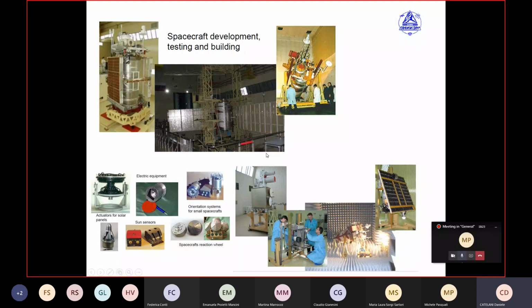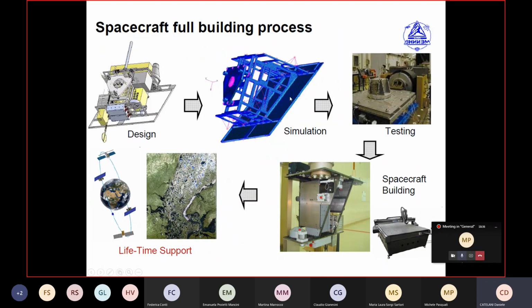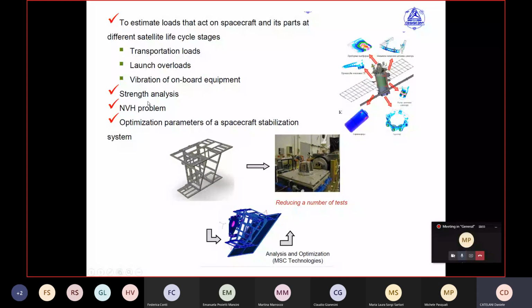You create the simulation equipment, you compare the simulation results with the tested results, and you can evaluate the structural problem, mechanical problem, thermal problem, and acoustic problem first in the simulation environment, and then in the test lab. The typical approach in this case is to validate the model from the structural point of view, mechanical point of view, etc., in order to reduce the number of tests.